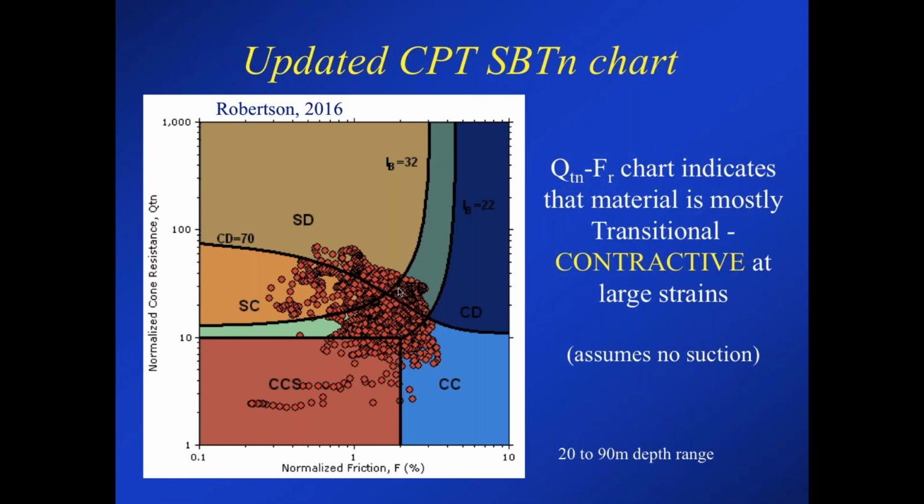And of course, a lot of the research on partial drainage is on soils that are contractive. And so, when you test it drained and then go to undrained, the drained value is typically 3 to 4 times larger than the undrained value, which is saying, yeah, this is a contractive material that if you test it undrained, it has an undrained strength about 1/3 of what the drained strength is. Very few people have done research on dilative material looking at the rate effect.